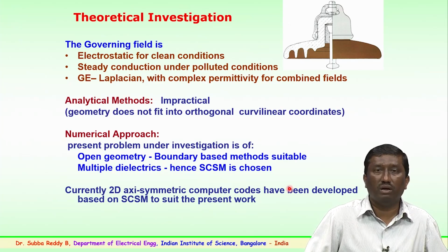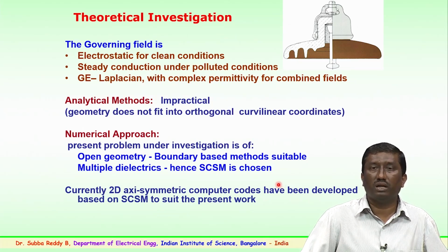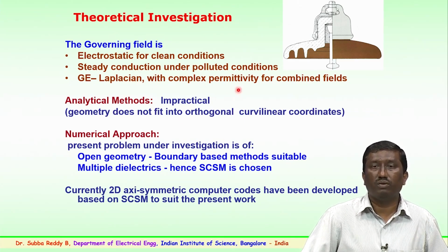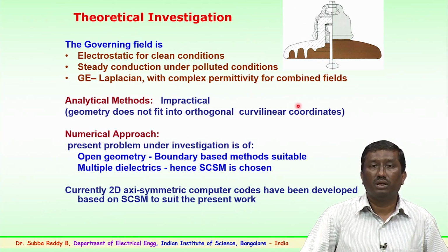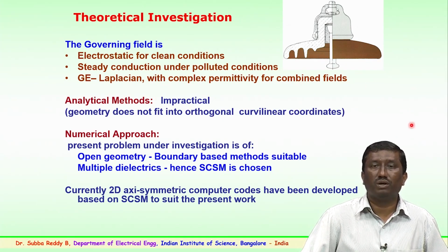So, we have carried out theoretical investigations where we have assumed the governing field as electrostatic, particularly for clean conditions, and steady conduction under the contaminated conditions. For the theoretical investigations, we have used the governing equation as a Laplacian with complex permittivities, particularly for the combined fields. Developing a model using analytical methods is impractical because the geometry of this insulator is so complicated, it does not fit into the orthogonal curvilinear coordinates.